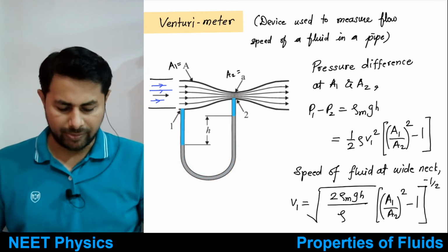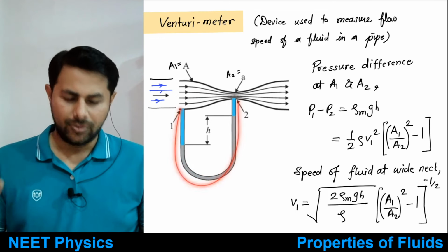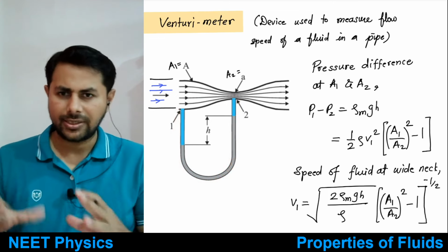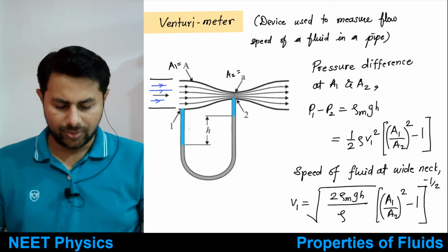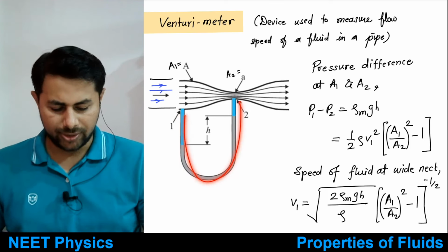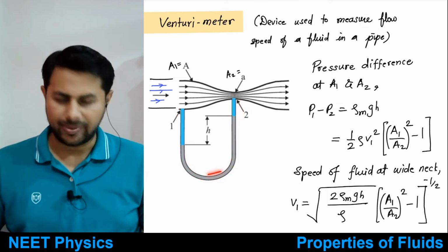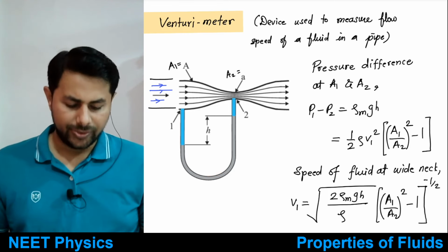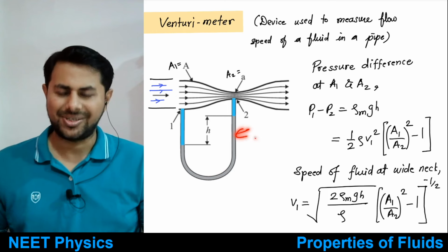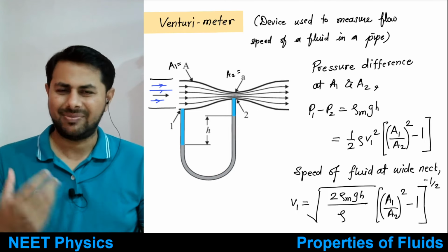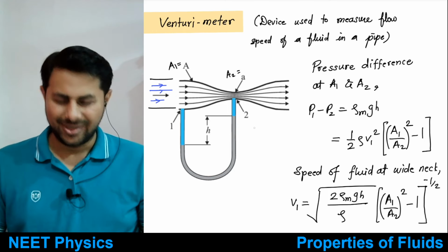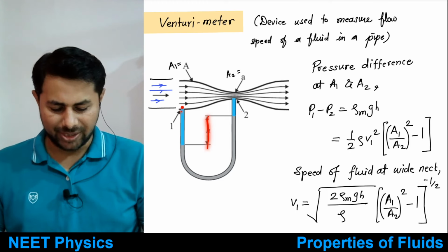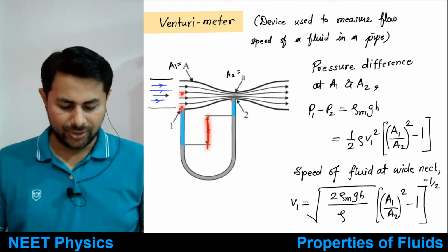All right. So then the pressure is measured using this manometer. A manometer is also connected to the Venturi meter, or you can say it's part of the Venturi meter. Mostly mercury is used in this manometer, but sometimes they might give you the density of the fluid that is used in the manometer. So you can easily measure the pressure difference here and here using what?